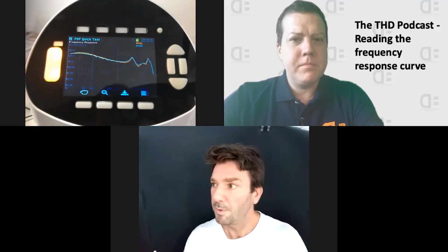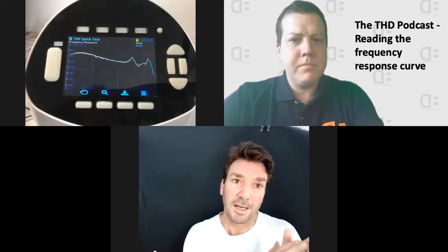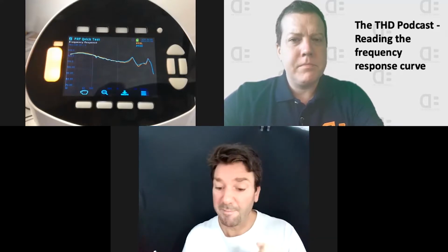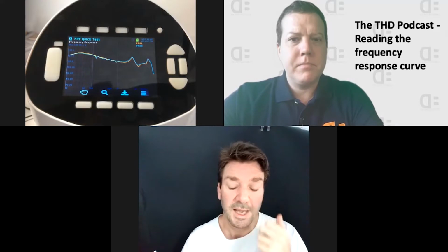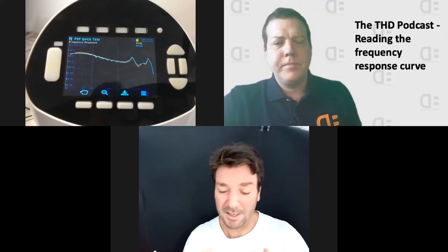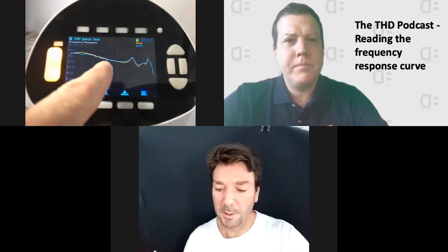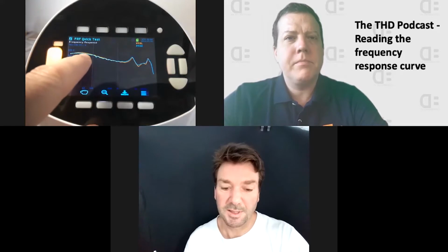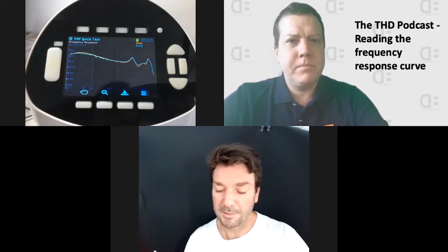If you know something about loudspeakers, at the very low frequency you roll off to 0, and then you have an F0, a resonance frequency, and it's flat from that point onwards. Headphones actually do the opposite, strangely enough, because it's inside a fixed chamber. From your F0 upwards, it's actually sloping down. This F0 is down very, very low, so it will slope down like that.